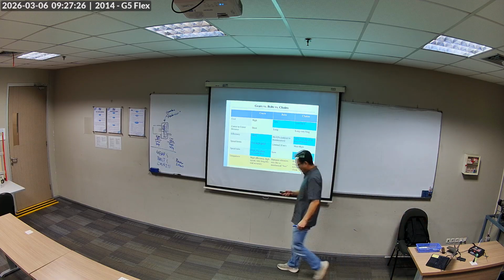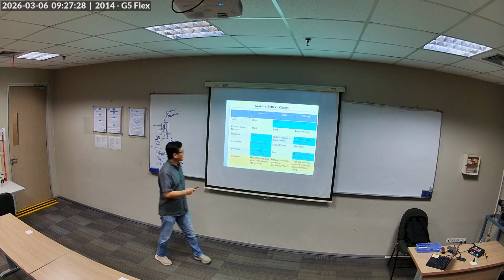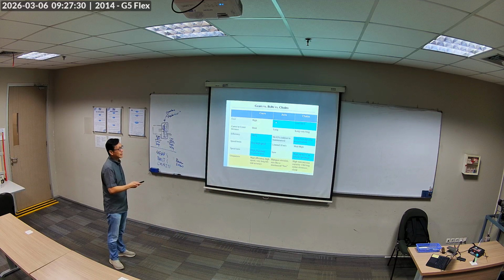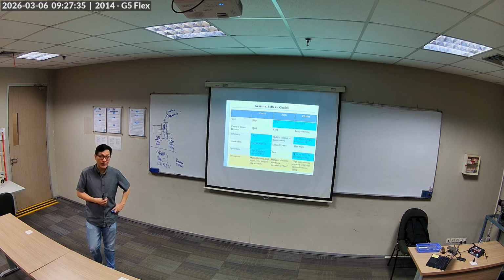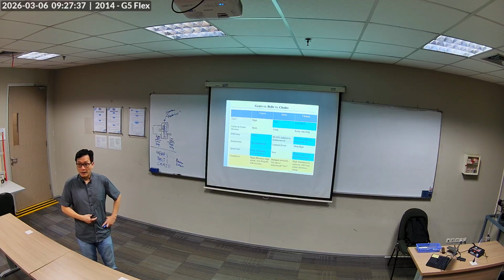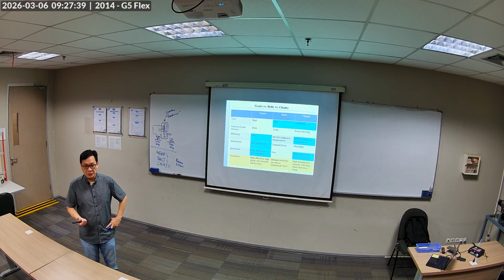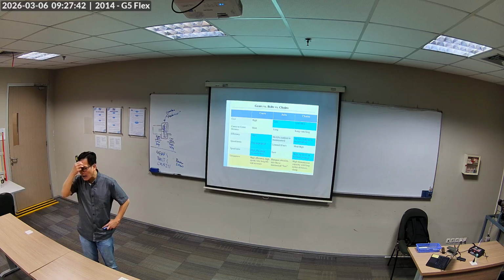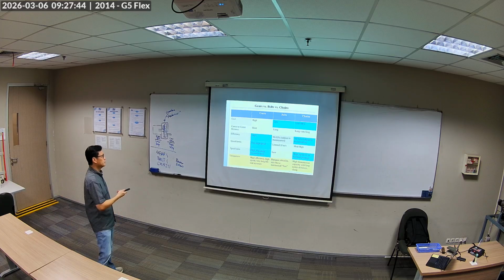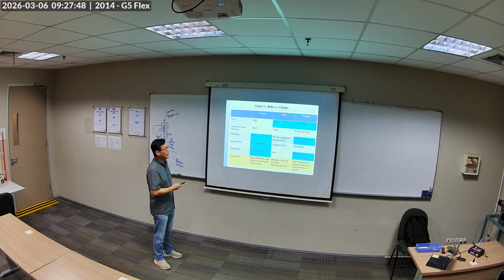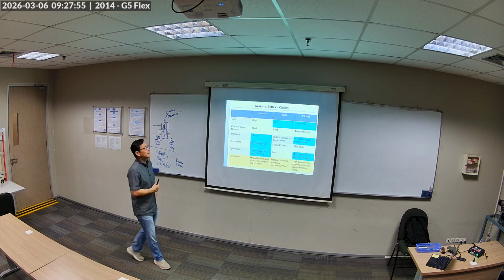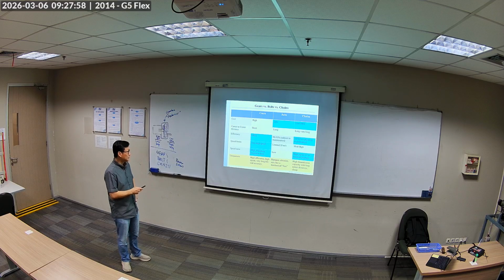Cost. Always comes out of cost. Gears, high cost. In fact, a lot of the gears are custom. So if you order a gear, sometimes you have to do a custom order. They'll make it for you. Stock gears are out there, not too many though. So this is why it's very high cost, low volume production. Belts are very standard. People replace them all the time. It's really low cost. Chain, low to medium cost.